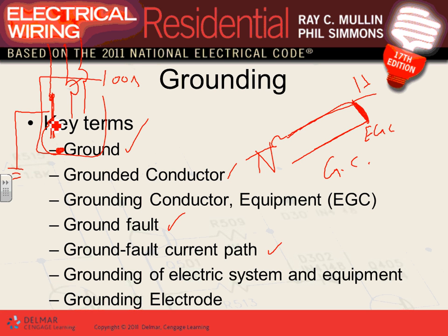Can I not ground the neutral? Yes. There are certain applications where we don't have a neutral, we don't bring it. Can I not ground the equipment? Yes, with some exceptions. The rule in the US is that 90% of the time your equipment must be grounded and your neutral must be grounded. Can I get you guys to understand that one? Ground the neutral as well as the equipment at this point.